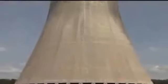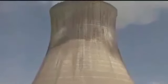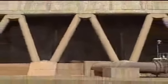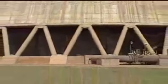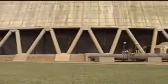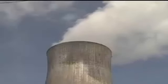In a cooling tower, heat is removed from the water in two ways, by convection and by evaporation. Convection is basically heat transfer to or from a moving fluid. In this case, convection occurs as the cool air flows over the water. The movement of the air causes heat to transfer from the water directly into the cooler air. Evaporation occurs when some of the heated water that's exposed to the cool air changes to vapor. The evaporation of some of the water helps cool the remaining water.